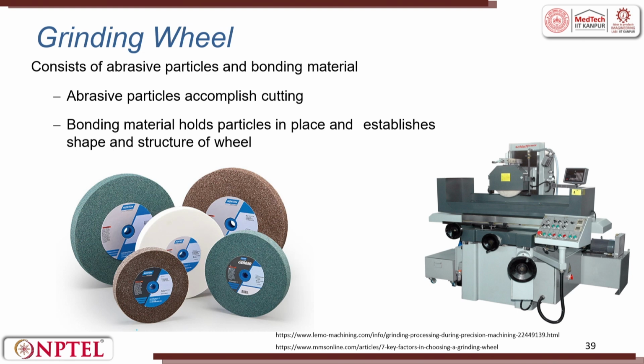So, this is how a typical grinding wheel looks like. This grinding wheel is mounted onto a grinding machine, and the grinding machine is horizontal. It is almost like your horizontal milling machine. So, here the thickness is not very large, so we do not generally have an overarm to support. You have it short and slender, so it is mounted directly to a spindle.